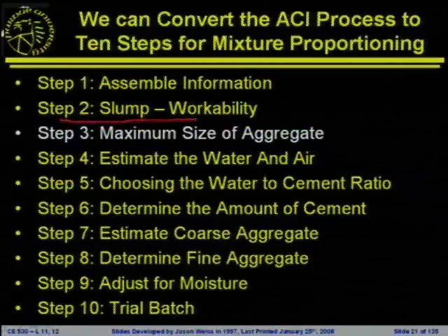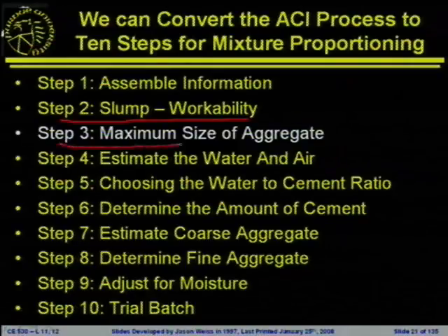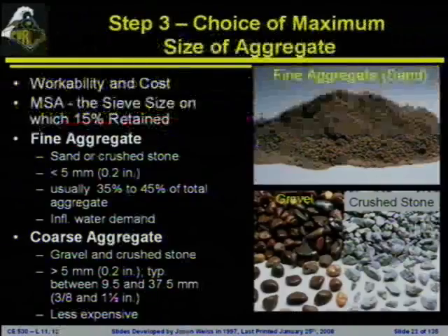So slump, and I will say at this point, slump is relatively arbitrary in the process when you select it. There's a table there to provide some guidance, but it's a relatively arbitrary step in the whole process. Step 3, estimate the maximum size of the aggregate.